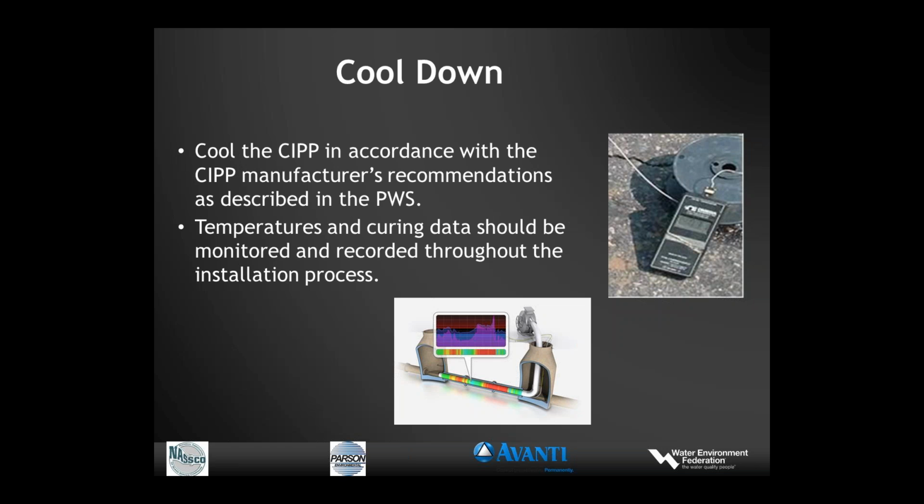At the bottom is a method that's been used for a few years very successfully, where a fiber optic cable is installed prior to the installation of the cured-in-place pipe. And once the cure starts, the temperature can be read at any location in the pipe at any time by anybody that has a computer or a smartphone. So it's a very, very powerful tool and is being used quite a bit in the industry. So whatever you want needs to be specified, either one.